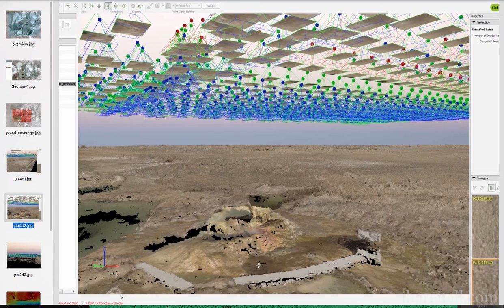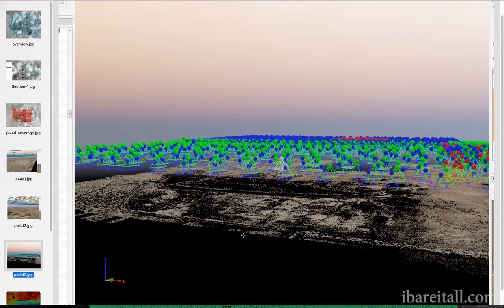So this is more of the point cloud data, because you can see it's a bunch of cubes, points or whatever, and this is before the 3D map is generated. So it goes through the process of generating your point cloud, and then you can generate the 3D map, and then generate all the other data that you may need for that. Here's another example of the point cloud, from a little further away.